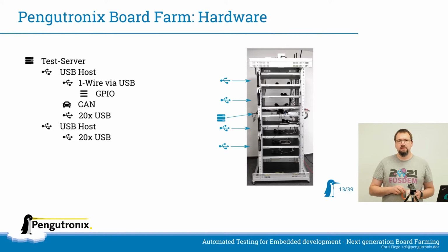What USB devices do we attach? Well, first of all, in the newer labs there is no serial server, so a lot of serial ports for UART on the one hand or RS-232 on the other hand. But we also have logic analyzers in our labs. We have USB device ports on our devices under test that we use for IMX USB loader or Android fastboot in the bootloader. And so, yeah, there's a lot of USB devices that sum up in the end. More on that a little later.